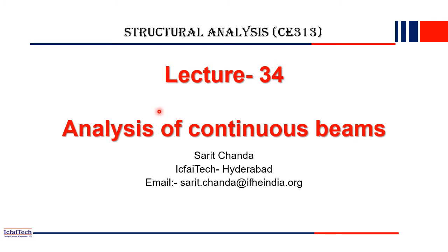If you recall, all the structures we have discussed till now are determinate structures. That is, we can analyze the structure using the equations of equilibrium. Already we know that in a 2D structure there are three equations of equilibrium: the summation of all horizontal forces equal to 0, the summation of all vertical forces equal to 0, and the summation of all moments about any point equal to 0. Using these three equations, till now we are analyzing the structures, and that too simple structures.